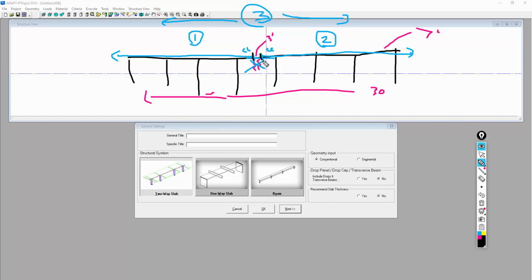We have basically 3 tendon types in this program. There's tendon A, there's tendon B, and there's tendon C. All 3 of these tendons can be classified using different shapes per span, so that we might have a reverse parabola, a straight shape, a partial parabola, a simple parabola if we zero out the inflection points. So these allow the user to enter different shapes. One of the restrictions, however, is that tendon A, I'll go ahead and put a square around tendon A, has to be modeled end to end.